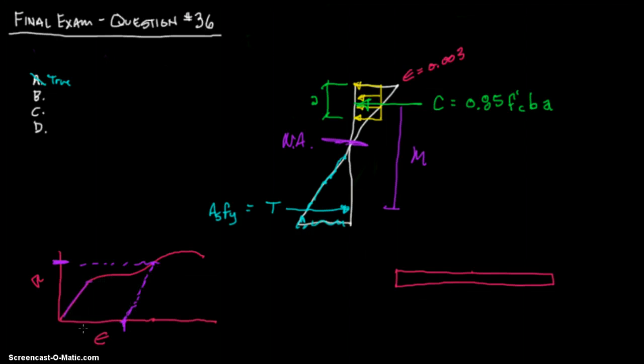So you will have permanent deformation. Right there is going to be your permanent deformation. And you will be able to tell in your steel. You'll look up at a building and say, hey, the ceiling tile's cracked, and the tile on the floor cracked, and you can tell there's a big old dip in your floor. Hey, we need to fix it. But since the stress right here went up, it didn't have a catastrophic failure.